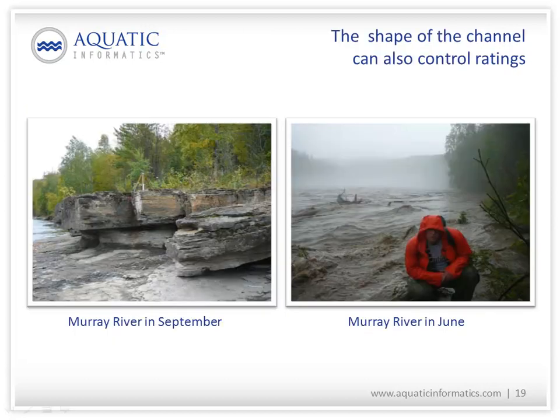Channel shape in many natural channels does not mean that you've got a steady increment of cross-sectional area as a function of stage, as shown in these two pictures from the Murray River, where the channel shape actually closes in on itself at higher stages and then spills over and gets into overbank flow. So with this kind of cross section, you're going to have a very complex rating curve.